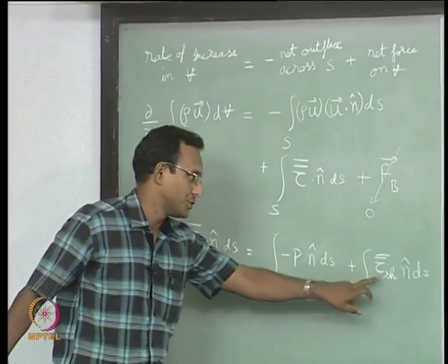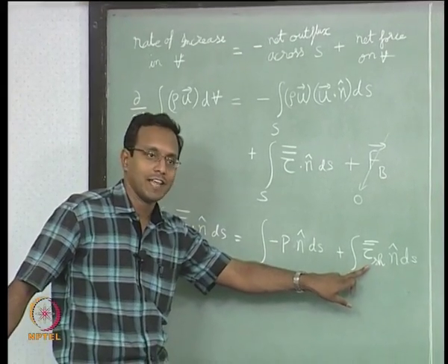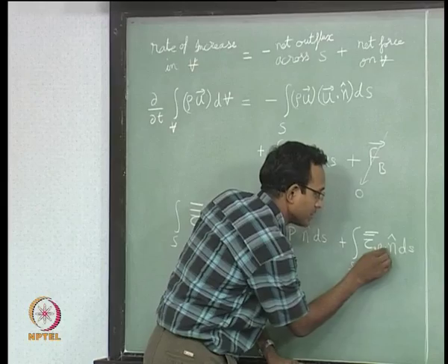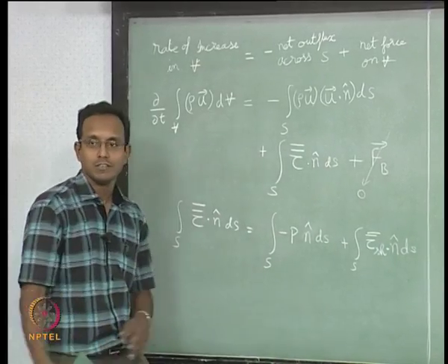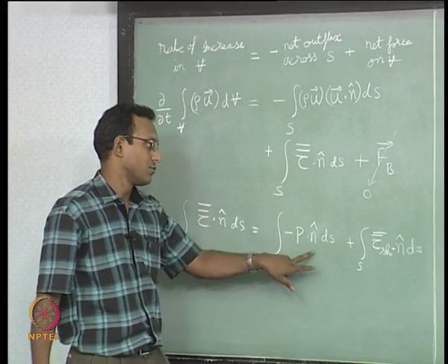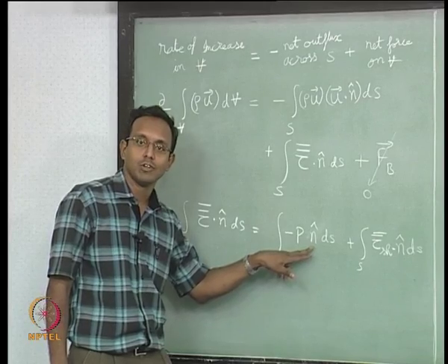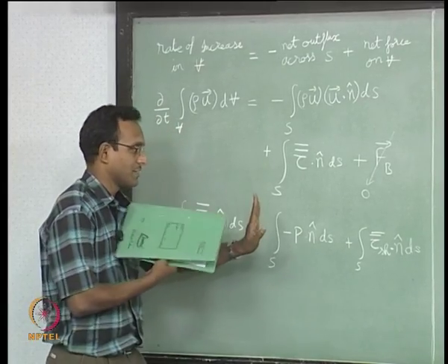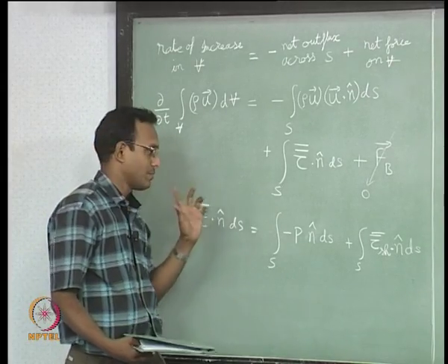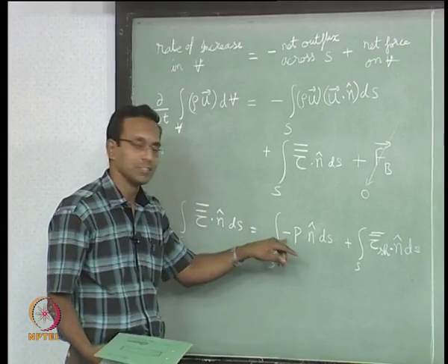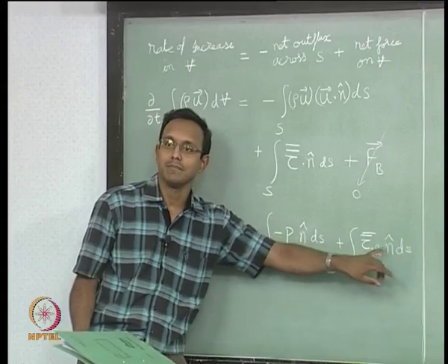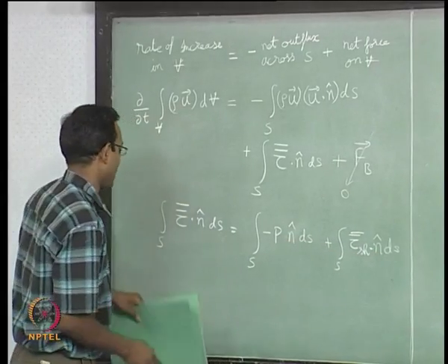and I am writing it as tau shear, which means all the diagonal components of this are 0, and then I have to take a dot product with the perpendicular surface vector, and the force is acting along the n direction, the normal force. If there is a surface and the pressure is acting from outside onto it, the normal is going to be out of the box and pressure is going to be inward. So, that is giving you this minus sign in there, okay. And in the shear force it will automatically take care of the sign based on this dot product, okay. It will take care of it by itself.